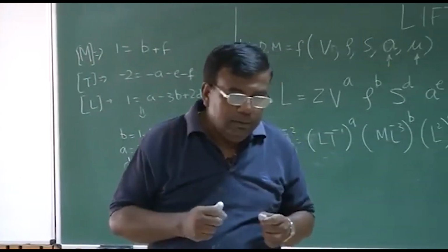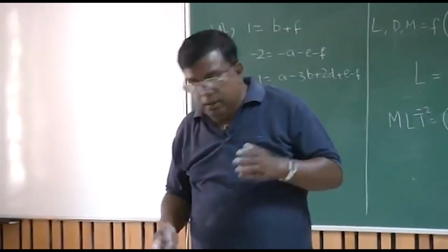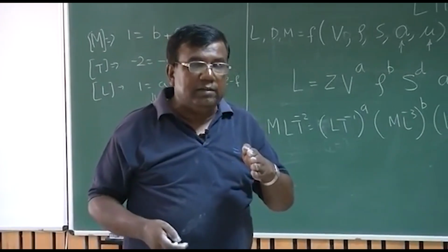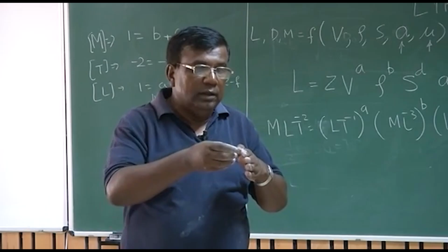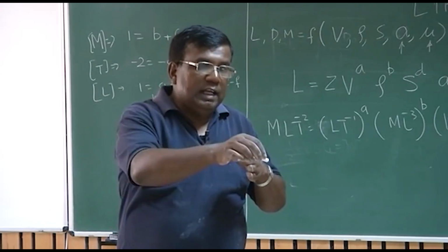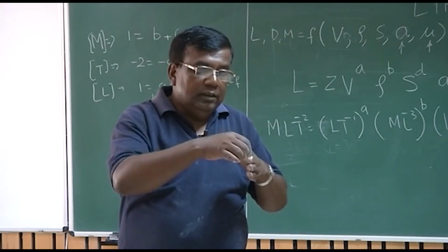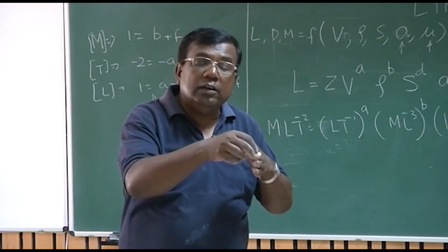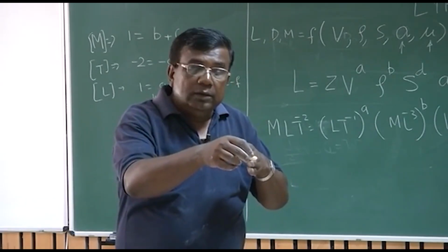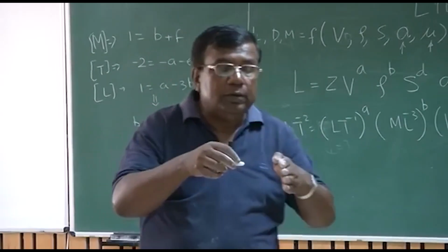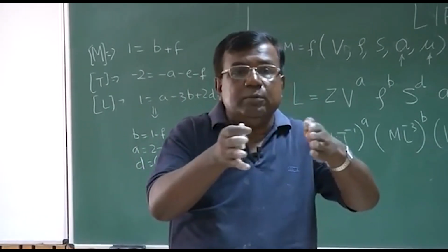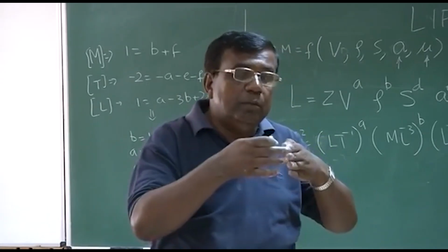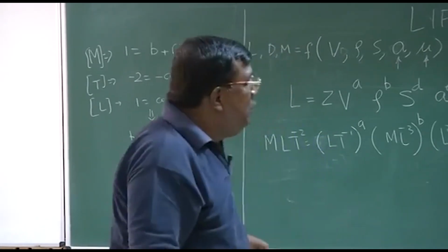Now think of, suppose there is a body moving like this, and the speed of this body is less than the velocity of sound. So what will happen? Before the body reaches another particle, this disturbance will reach there earlier, because the body speed is less than the velocity of sound. So when it moves, the particles will arrange themselves based on the disturbances they have received already before the body has reached there, right?